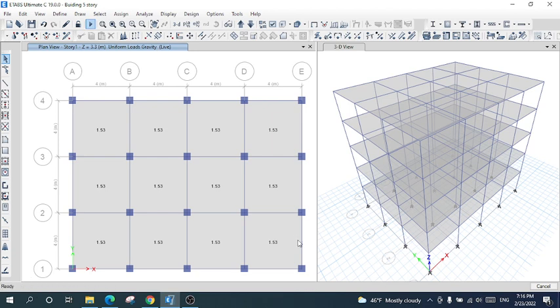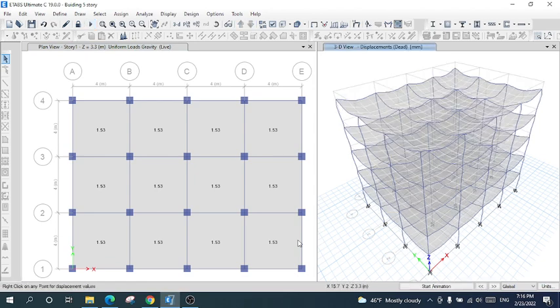The main agenda of this tutorial was how to scale earthquake records to match the target response spectrum, and that purpose we have achieved. Additionally I have defined other structure sections and applied the loads and other things. Now the analysis has been completed. You can check the analysis results and you can start an animation with others.